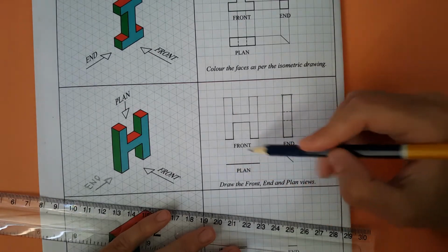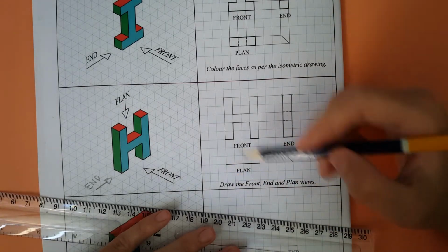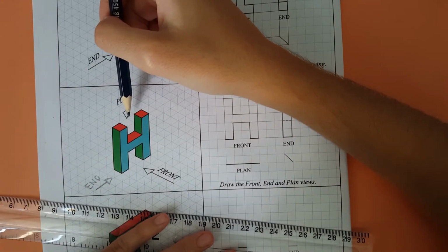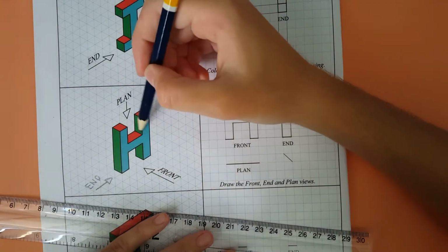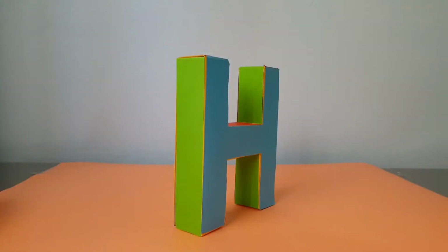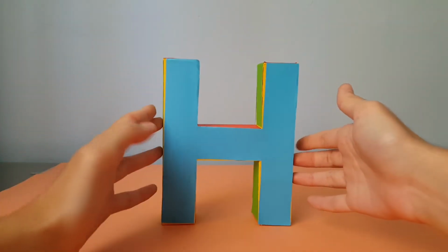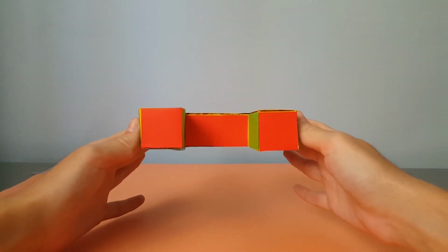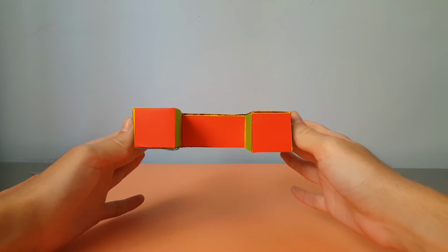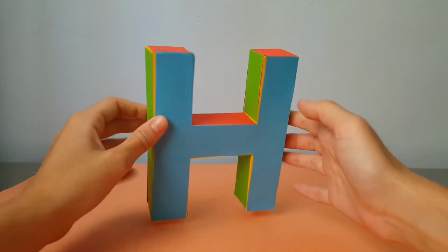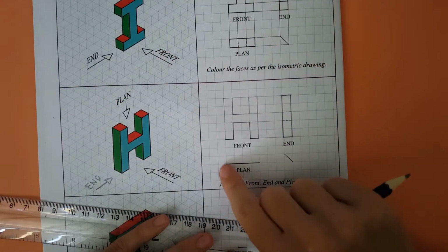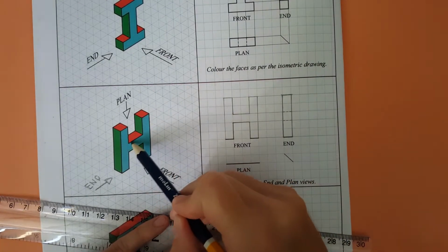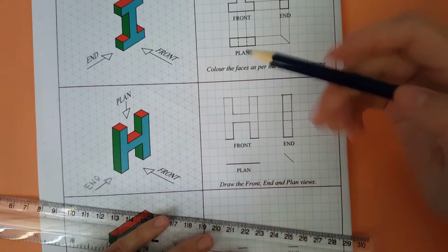Now onto the plan elevation. And on the plan, we have to draw whatever we see from the top view of our solid block. We see this square, this rectangle, and the other square. Now to help you visualize once more, this is how the plan should look like on our orthographic projection drawing of this H. On our textbook, as you can see, we have the starter line, which represents these three lines on our isometric view.